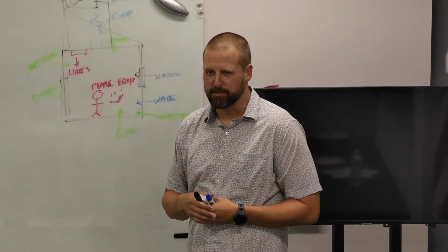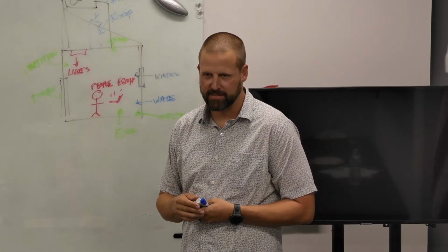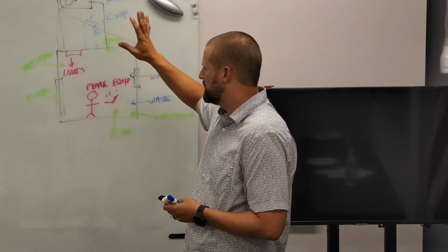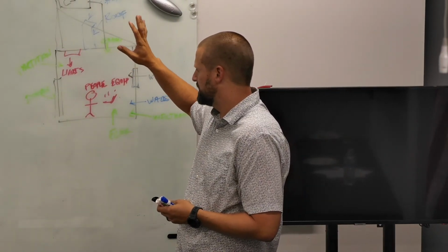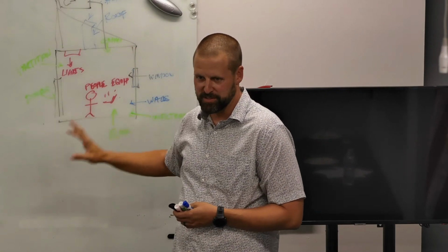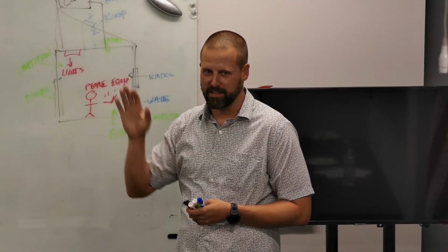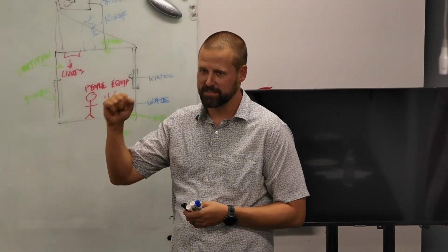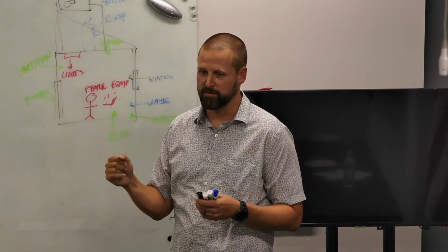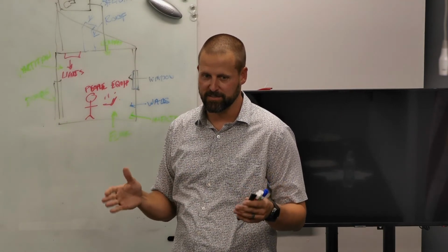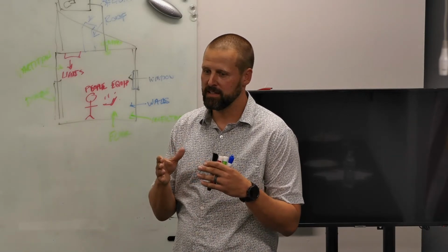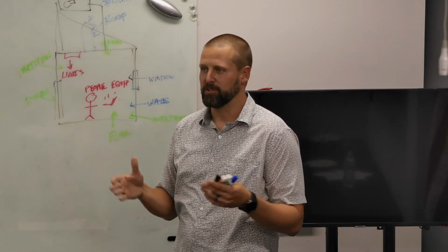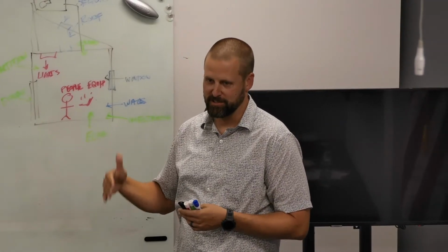As we go through these items, it's important to understand that we make a lot of assumptions for this, and there's safety factors that can be applied here, and at the system level, so it's important for us to know where our safety factors are. That way we don't oversize or undersize equipment by adding safety factor on safety factor.